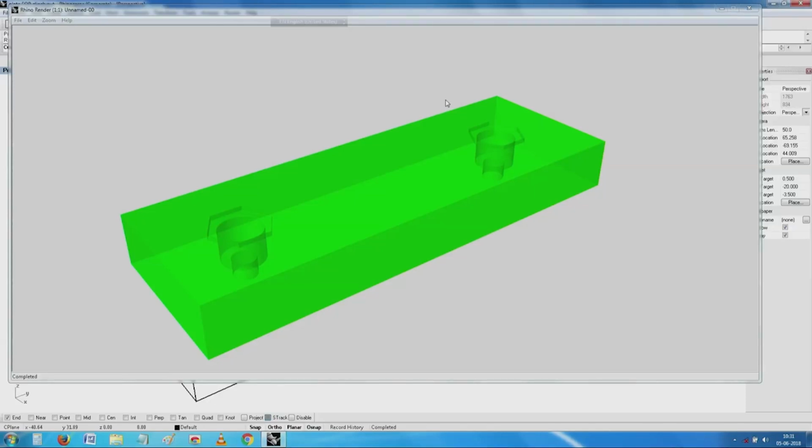What we have there, just for the purposes of illustration, is a solid I have created in which there is a provision for putting a threaded insert. In other places, say if it were aluminum and very small, we put a riveting nut or something. If it is sheet metal, on one side we have a thread nut, or if it is a casting, we use something called a helicoil insert.